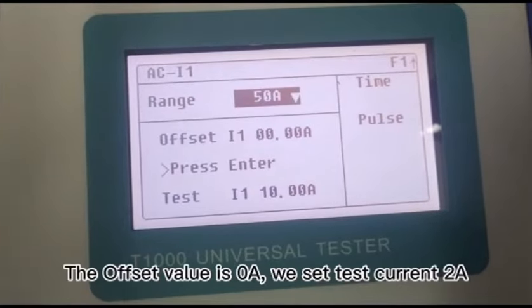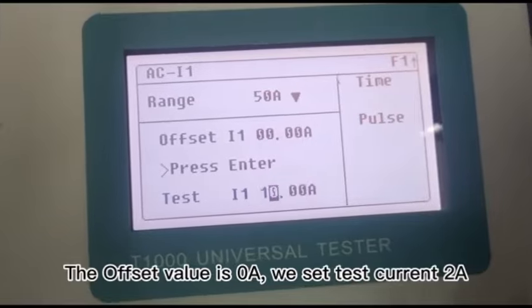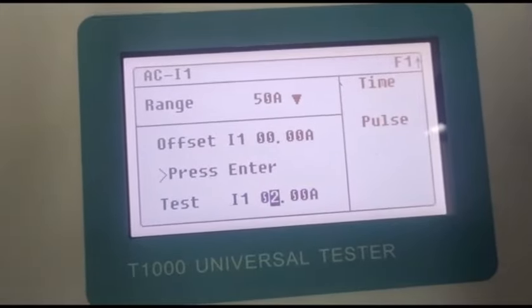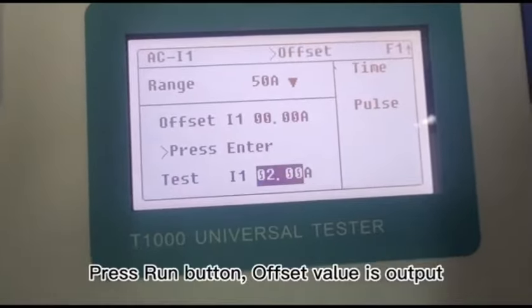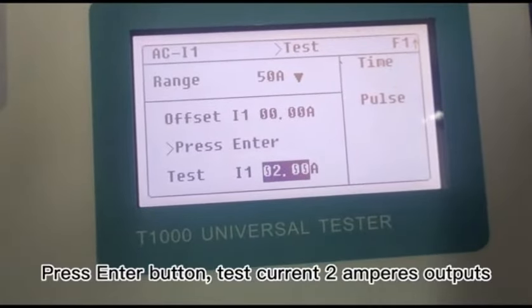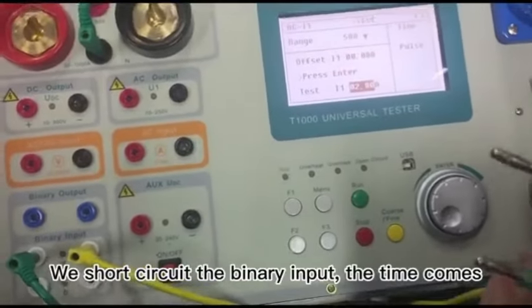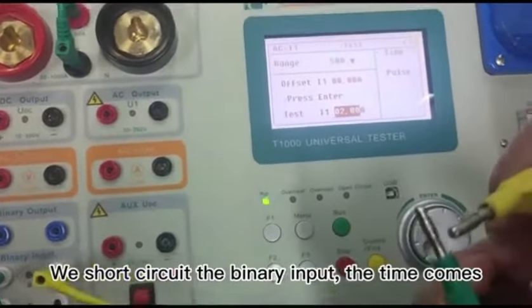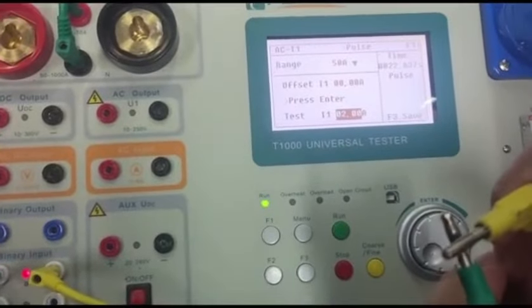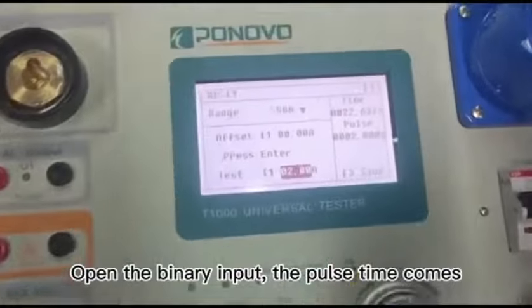The offset value is 0 ampere, we set test current 2 amperes. Press Run button, offset value is output. Press Enter button, test current 2 amperes outputs. We short circuit the binary input, the time comes. Open the binary input, the pulse time comes.